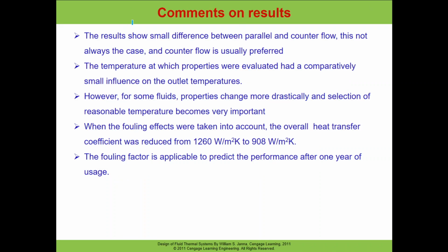So what comments can we make for this solution? The result shows that there is a small difference between the parallel and counterflow performance of the heat exchanger. The counterflow performance is usually preferred because it gives a higher rate of heat transfer and a higher change in the fluid temperature.